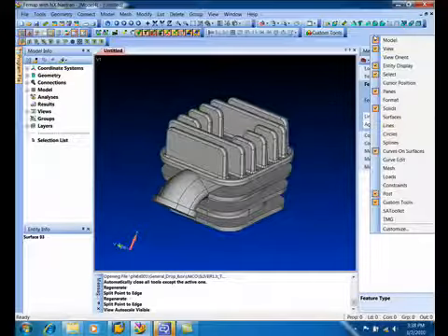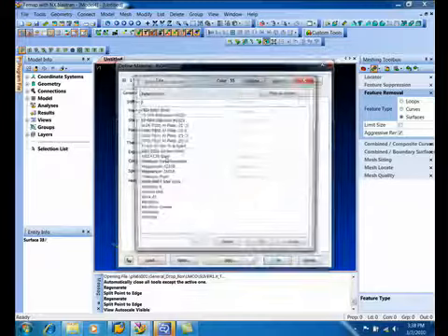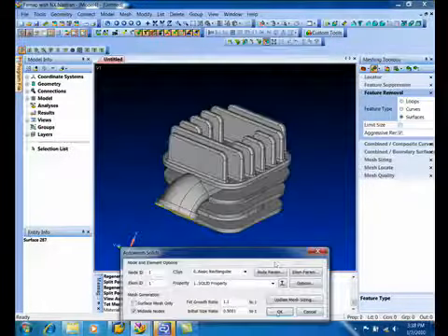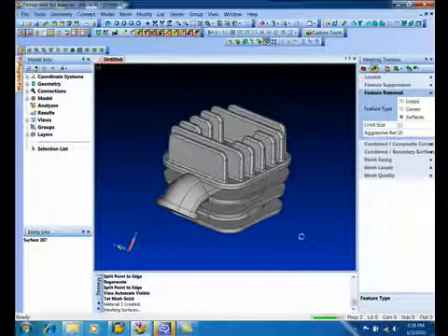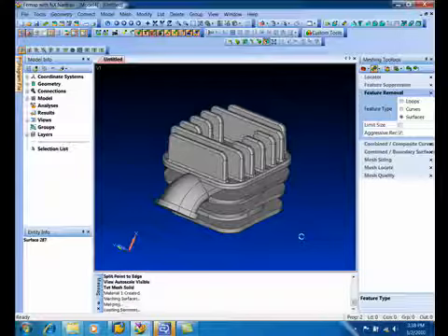Let me bring up the meshing toolbar, and we'll just say mesh solid. Pick a material. Let Femap pick the mesh density automatically. Feed it through. The surface is meshed.